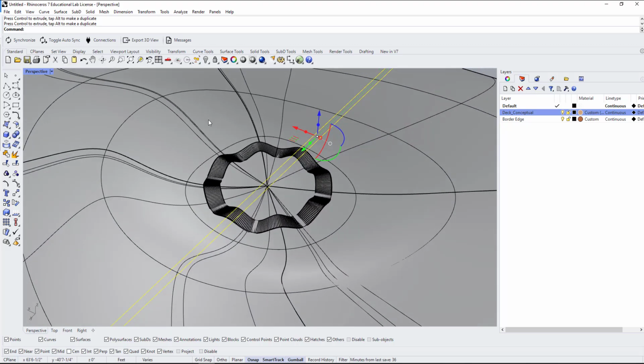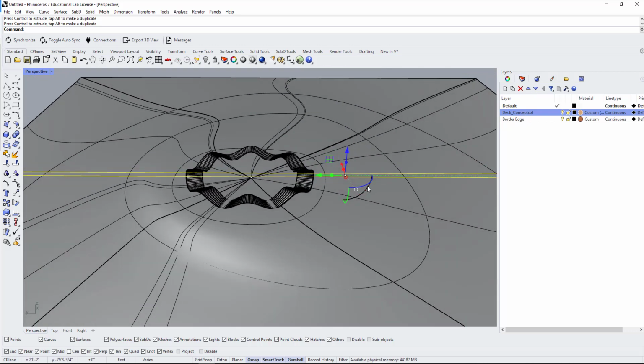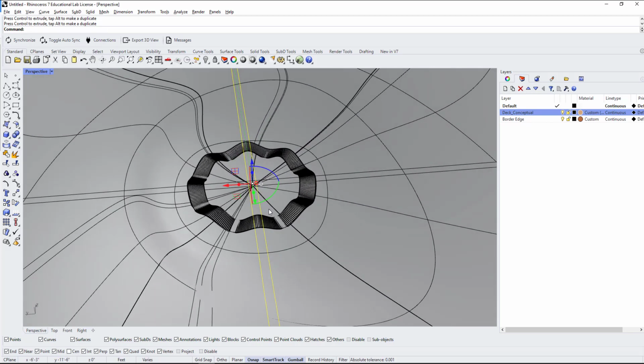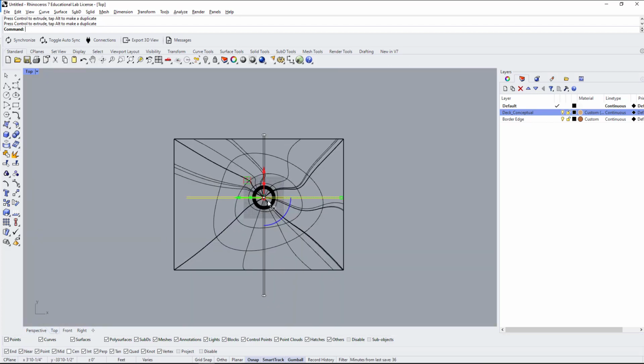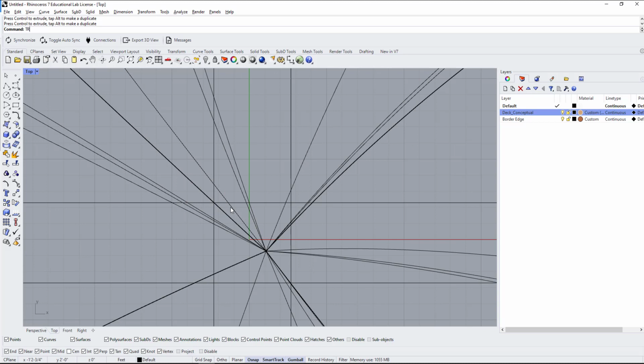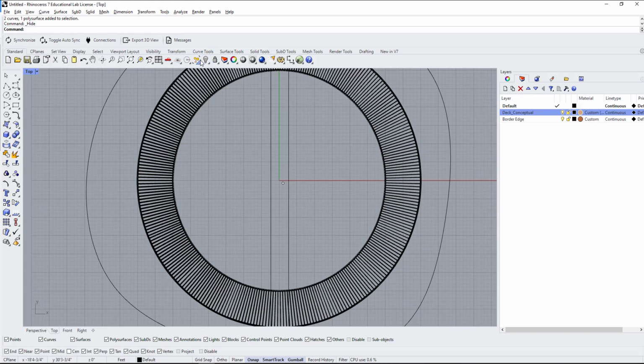One of the ways you could do that is to alt and click on that arc and type in 90. That way you'll have a copy that's rotated at 90 degrees. So let's move them in place. Let's trim them properly for roads. So I'll hide my site.